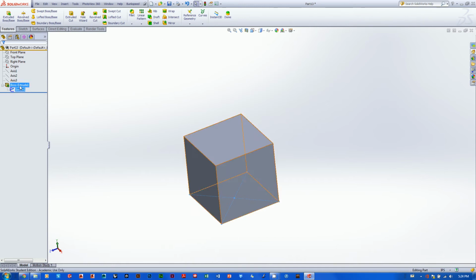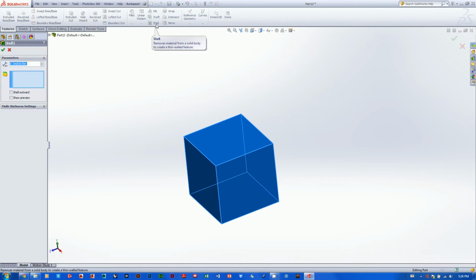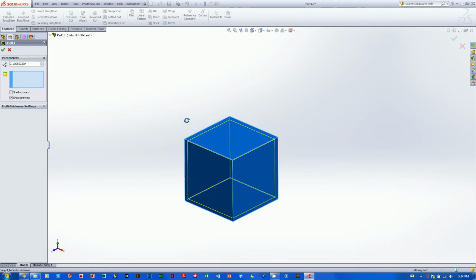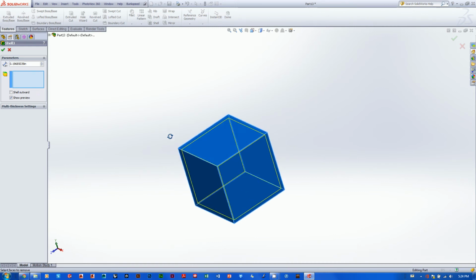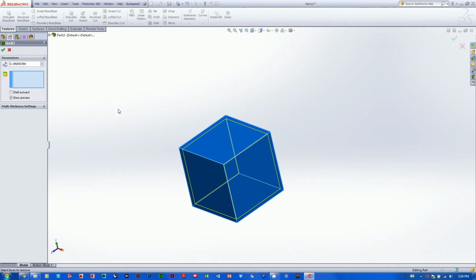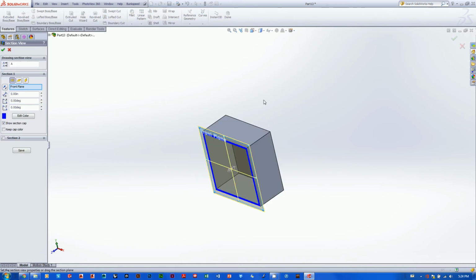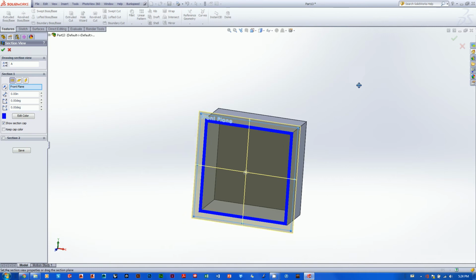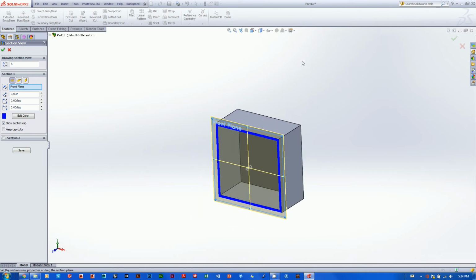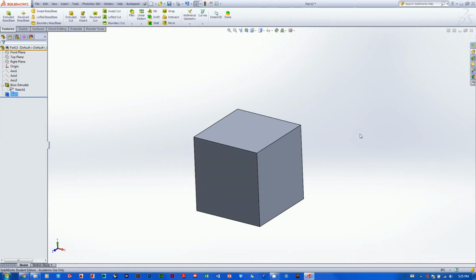So there we go. So if I go here and I click on boss extrude, and then I fire off the shell tool, I don't add any faces. I can go here to show preview, and then I get this nice preview. So because I selected not only the faces but also the body by selecting the thing that created both of those things, which was the boss extrude, it allows me to fire off the shell in the way that I want. Hit the green checkbox, take a look at the section view, and realize we have succeeded in our attempts to hollow out this cube with a certain wall thickness. There we go. So we'll exit out of that.